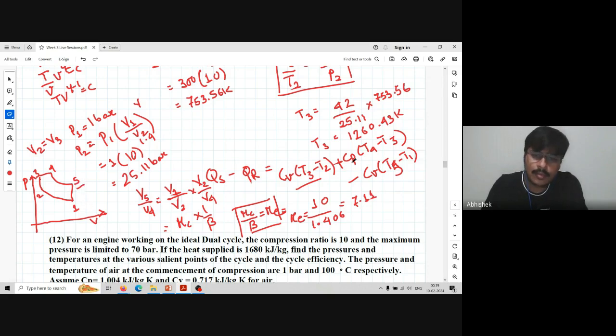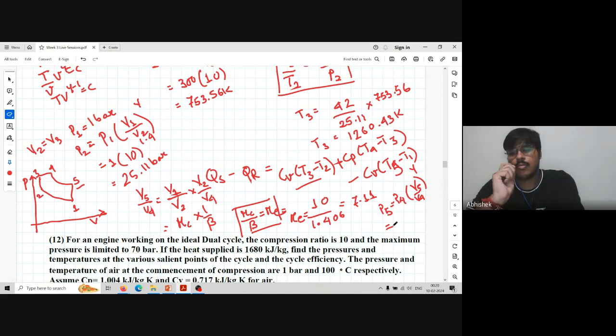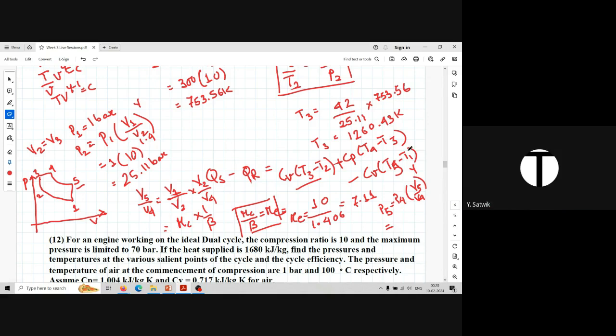Now you have this V5. Can you calculate P5 now? Yes, sir. P5 is P4 into V4 by V5 to the power gamma. Sir, what is P4?